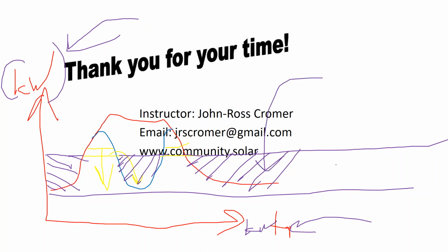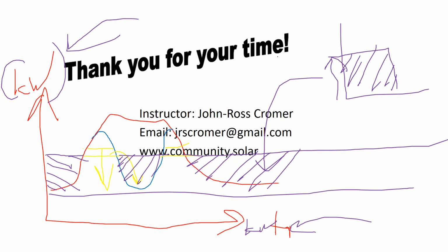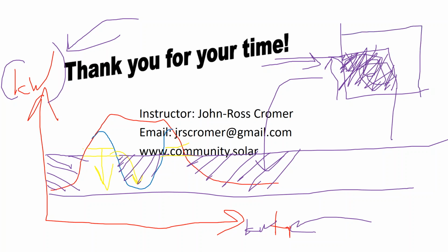Basically what these valleys represent is dirt cheap electricity. And what we see is utilities may be going, instead of a kilowatt hour rate structure based on volume under the curve or a demand rate structure based off the amplitude, they're trending towards more block-based rate structures where you stay within this block of kilowatt hour and kilowatt parameters, and if you exceed the block you get into a higher rate tier.